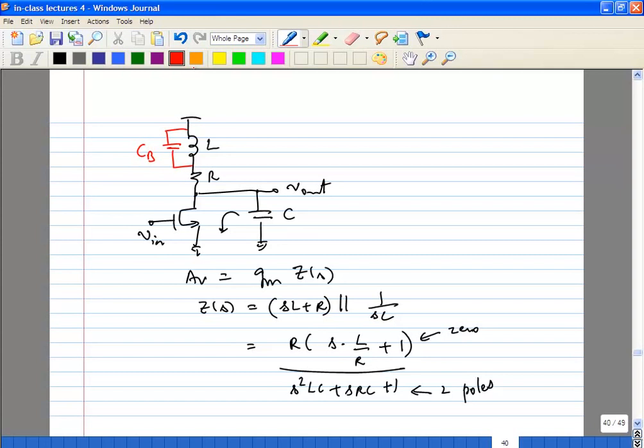It's called a bridging capacitor because it bridges across the inductor. What happens is there will be some resonance between L and CB that actually also helps to boost the bandwidth. And you can find conditions on CB value and on L value, for the same conditions we put in before: maximum bandwidth extension, maximally flat, and so on.